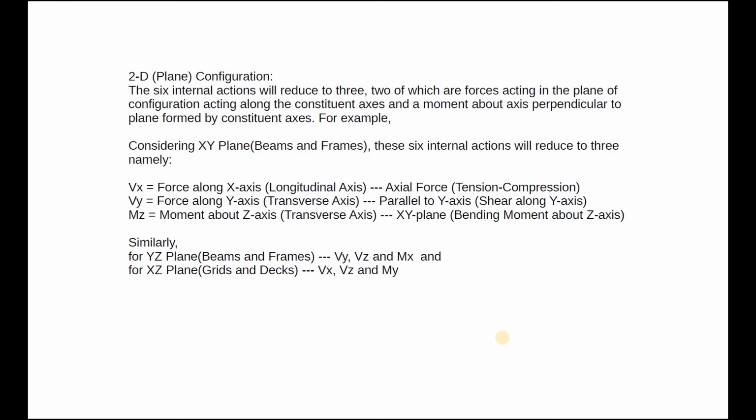Notice here that for the geometries lying in a plane, the rotation component is always defined about the axis perpendicular to the plane of the geometry. For example, over here you can see that the geometry is in xy plane. So the bending moment is defined about the axis perpendicular to that. Axis perpendicular to the xy plane is z. So the rotation component is defined about the z-axis.